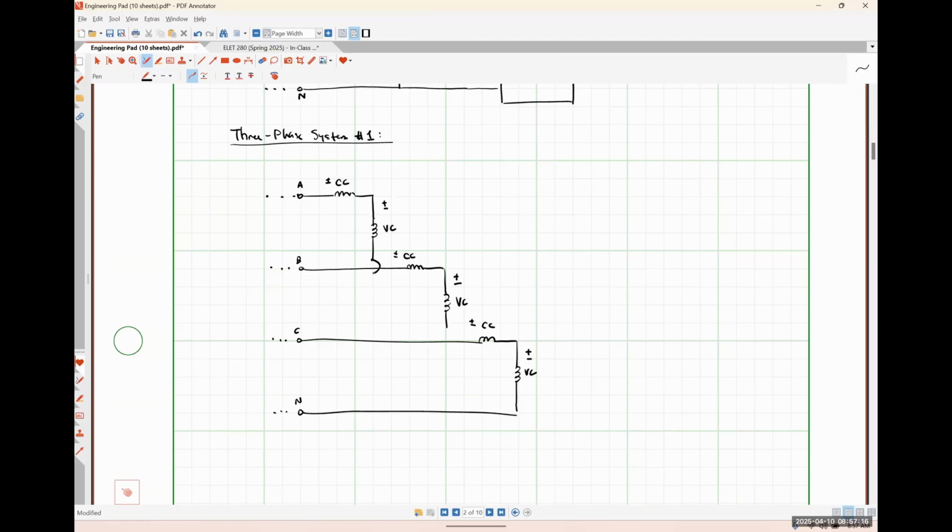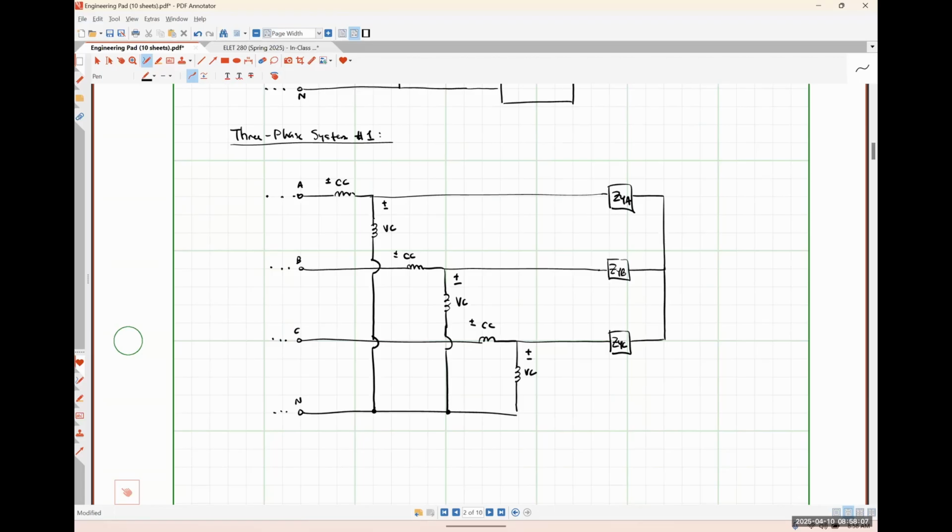Let me jump this guy over. Essentially, I'm going to have to tie the negative polarity terminal, or the bottom terminal, of the voltage coil down to this neutral connection on each phase. And then I'm just going to extend these wires way over here to connect my actual load: ZYA, just in case we don't have a balanced system, ZYB, ZYC. Neutral like so. And just putting boxes around our watt meters.